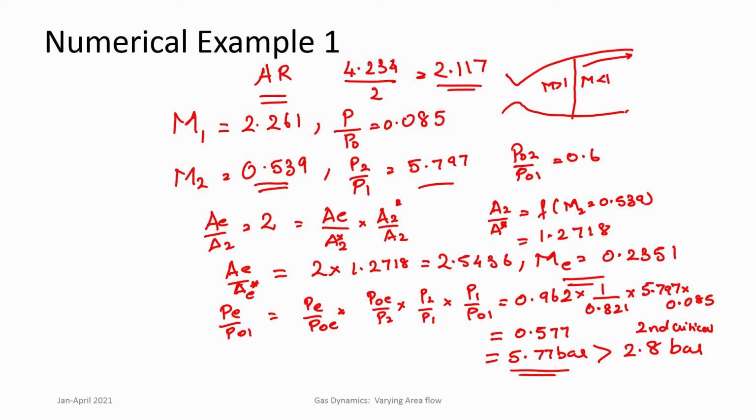The pressure ratio across the nozzle is often referred to as the nozzle pressure ratio, that is NPR. So in many places you will find NPR. NPR is always back pressure by stagnation pressure, or vice versa, P naught by PB. It is not the exit pressure. So exit pressure can be different when the nozzle operates in the under expanded or over expanded regimes.